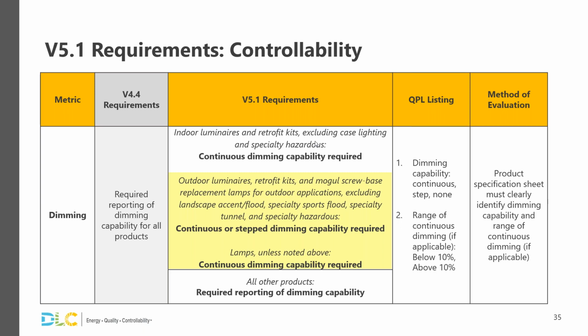And then the last one I'll hit here on controllability, a number of questions about the dimming of TLEDs, about how that is possible or lack of infrastructure in the field. All valid points. The way that we see TLED dimming being accomplished could be a variety of fashions. It could be through a dimmable fluorescent ballast. Admittedly, those are not common in the field. There are some of them out there, but a type A TLED that would be compatible, that could be dimmed through a dimmable fluorescent ballast would comply.